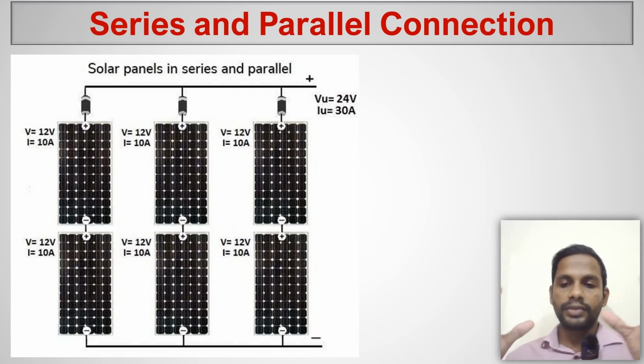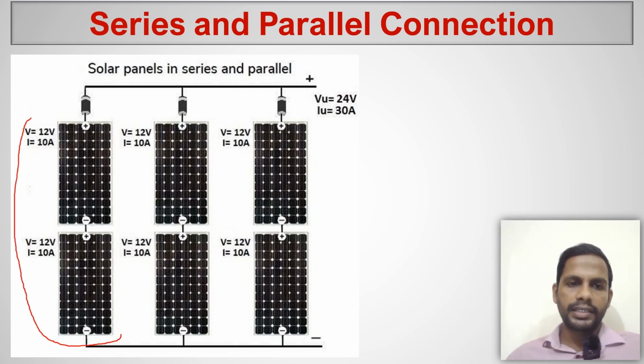So in an actual solar PV system, your rooftop solar PV or somewhere else, we have both series connections and parallel connections. If you look at these two panels, I'll draw something over here. These two are series connected. Look at this, this is a string. We can call this String 1, because these two modules are series connected.